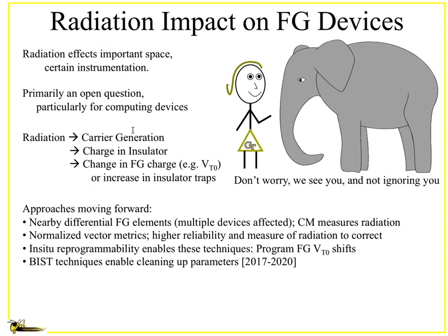And so thinking about that is important, but as we understand with some of the other floating gate aspects in terms of retention and so forth, it is probably a little more complex depending on how you use it. And there seem to be some interesting questions still to be asked of how you actually utilize some of the same circuit techniques in this space, because there may be some good robustness and possible opportunities there. Certainly you have the opportunity of having close differential floating gate elements, because you have multiple devices affected in scaled down structures, while at the same time the common mode tells you what your radiation levels are, and so you can use that to help do some correction.